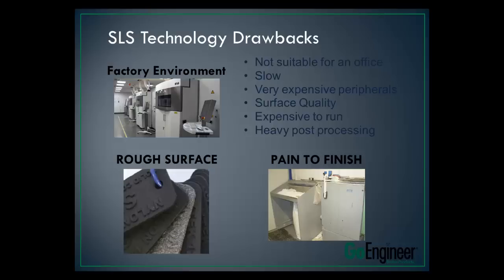And again, they have kind of rough surfaces. What I've done in the past, except with living hinges obviously, is impregnated this with super glue also. It makes it a lot easier to sand, a lot easier to paint and finish. It gives you a nice solid thing. I've actually coated these with a casted, 2-part urethane, to sand and finish these models too, and you get a pretty good result. But again, it's really time consuming once you get the parts, the post-processing, all that other stuff.